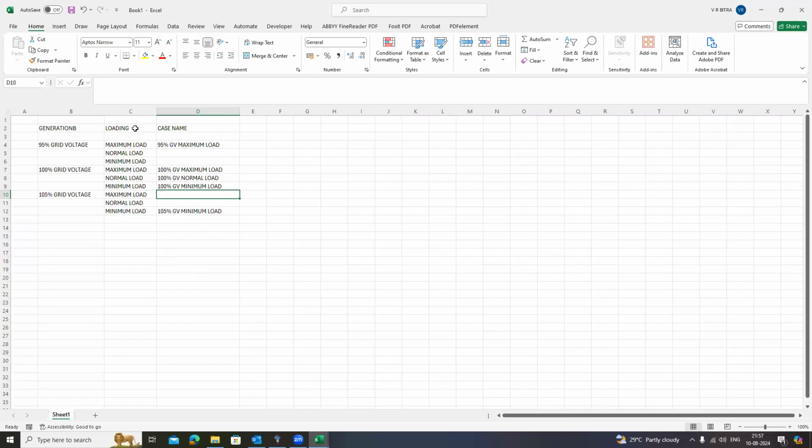And if you want to run the other cases, yes, you can perform and validate those also. But logically, what we are running is these two extreme cases. If you run these two cases, that is going to cover both the extremes. One gives the minimum possible voltage and the maximum loading, and the other gives the maximum possible voltage and minimum loading. So no other case goes beyond these extreme results, and you can really neglect the remaining ones. And if the customer is asking you to do them, that's not really going to make any sense.